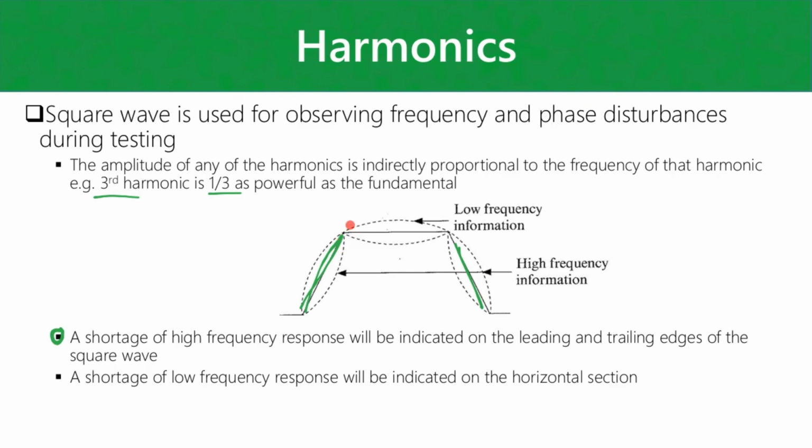And if you get any deformation of the flat part, basically the maxima and minima on your square wave, that's an indication of low frequency response or shortage of low frequency response. So basically your circuit is filtering out some of your lower frequencies. Okay.